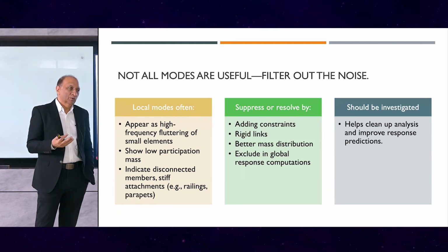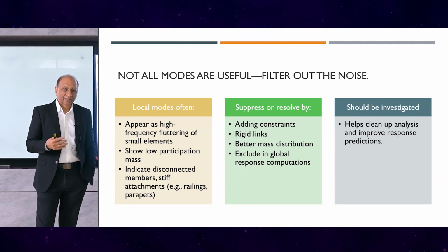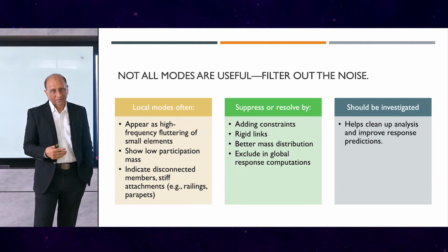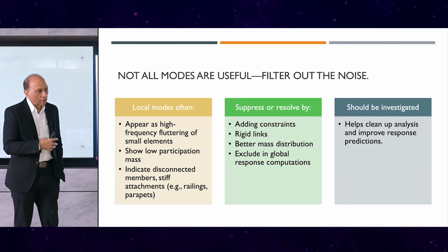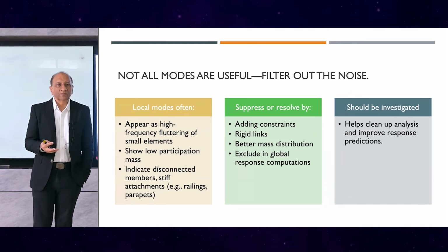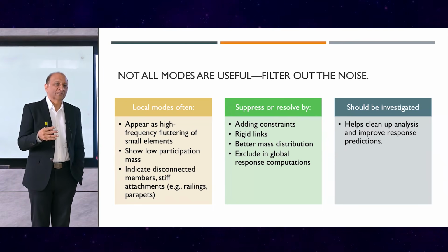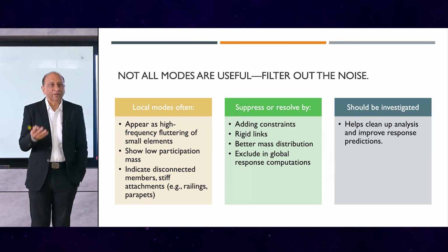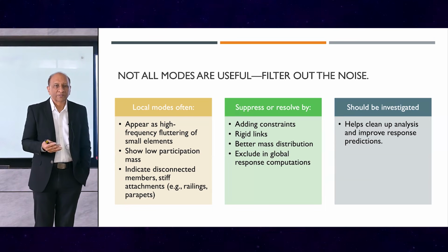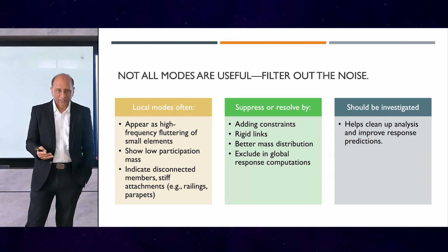So the next point we come to is that not all modes are created equal. That means we have to filter out the noise, because when you make a structure, you have all kinds of components there and everything is vibrating. So it's quite possible that some things are vibrating before the structure is vibrating, or they are vibrating in between the modes, and they will disturb or disrupt your main structural response computations.